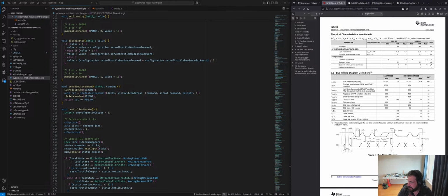Yeah, this is going to be my first time using it. Ironically, I put this sensor into this robot years ago, and the whole thing is like a Raspberry Pi. I think the logic side only draws, in the worst case, about 20 watts. So one of these big LiPo packs that I've got can be running at full power for like 5 hours before the batteries drain, and it's rarely ever running at full power. You can plug it in the morning and it'll last all day, so I never really bothered getting around to using the current sensor. So this will be the first time.